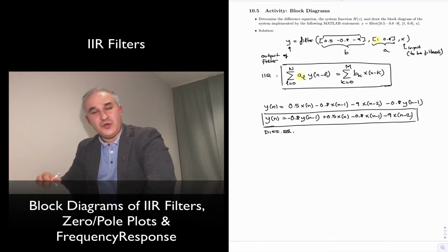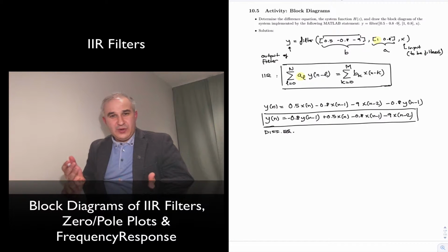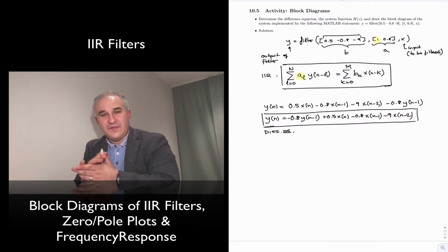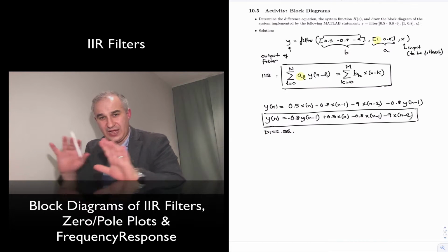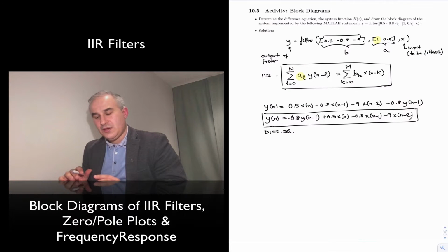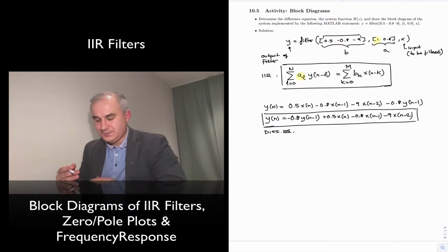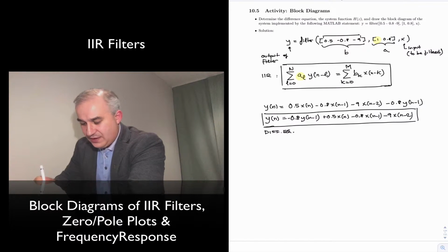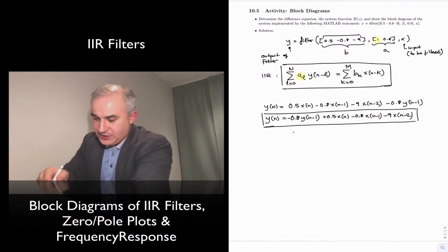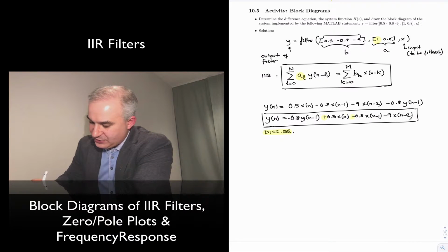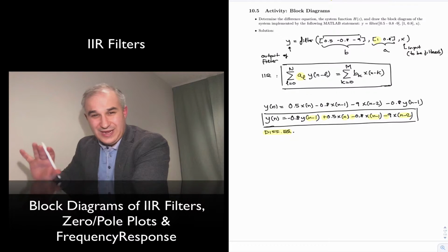And so in continuous time, in analog, if the circuit is active, typically you have an operational amplifier and then resistors and capacitors, and you can have multiple stages to have faster roll-offs. What you are implementing is a differential equation. In discrete time, what you have is a difference equation, the analog of the differential equation, and what you need are additions, the delay operator, so you need to be able to delay and store,